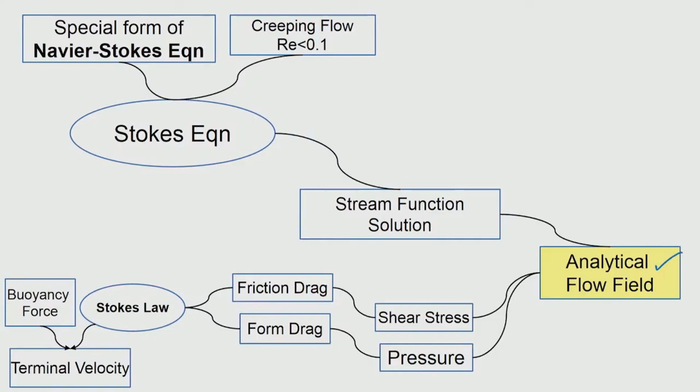So, technically the problem is over, but we now want to take this a little bit further because of a particular metallurgical application that we normally are familiar with. So, what we do is that we will use these flow fields to arrive at the pressure and shear stress distributions. So, both tau and sigma, that is basically the r theta and r r, and here pressure. So, we want to look at these quantities also, and how do we get these?